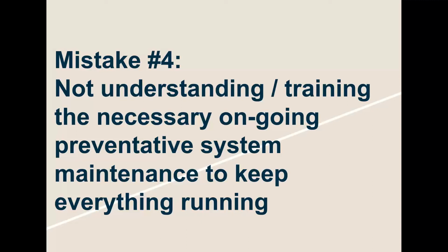But if someone's calibrating once a year, they may not be. So ongoing training as to how the equipment works goes a really long way toward having equipment that is working the right way, is not drifting so much, and is not giving you so many false alarms.